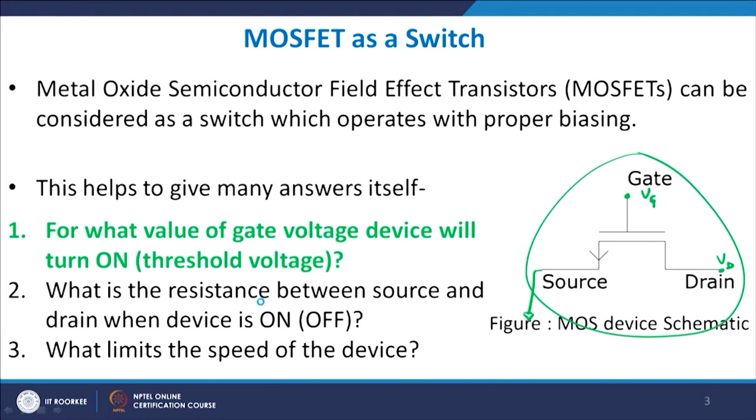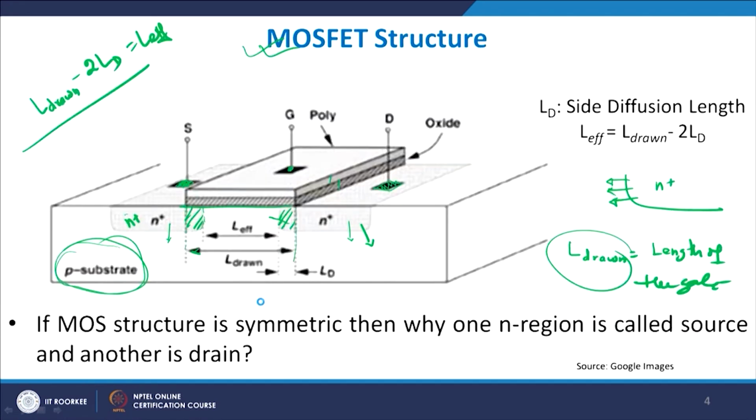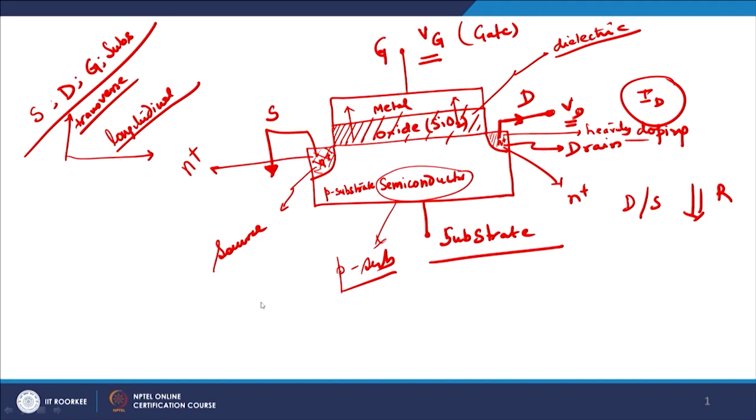So from this basic idea, let me see how it works in the switch. Now in our previous discussion, when we were taking up the basic concept of the MOS device, if you look very carefully, if you do not apply any gate voltage, I have a p type substrate here, which will have electrons as minority carriers. We have already discussed this point. However small, there will be some electrons available here. Also the source and the drain will have a large amount of free electrons. As a result, this forms a p-n junction diode.